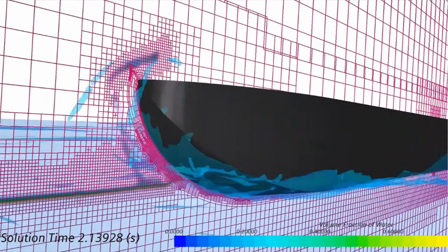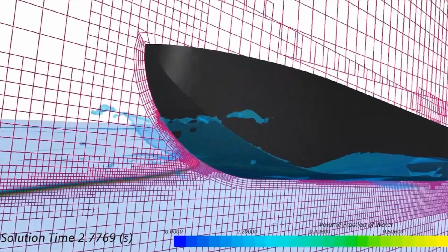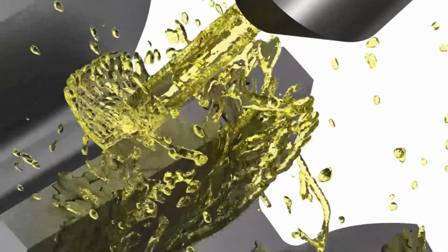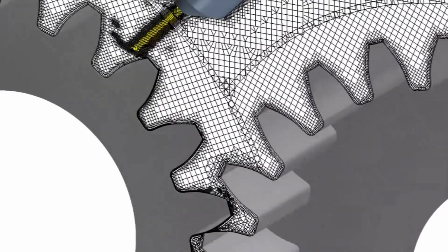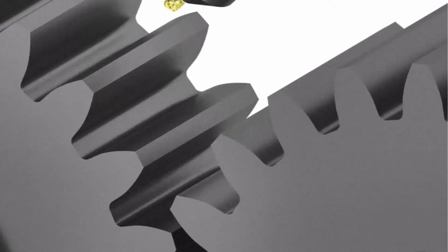For example, the free surface model-driven AMR intelligently refines cells to resolve the gas-liquid interface, reducing smearing. And the overset mesh model-driven AMR intelligently ensures that cell sizes at the interface are compatible. All of this without any user interaction.